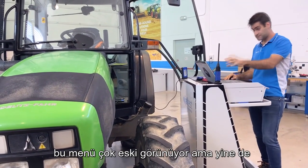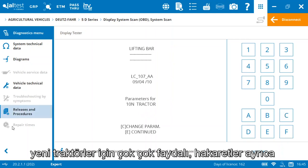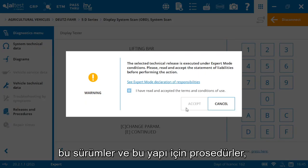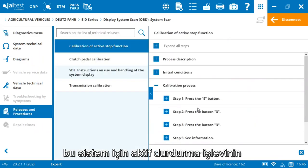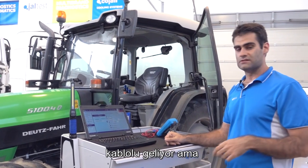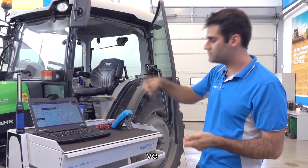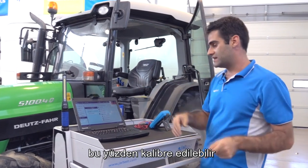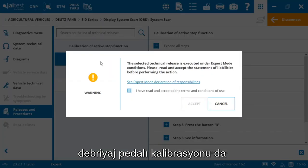Nevertheless, this menu looks very old, but it's still very, very useful for new tractors. Jaltest also includes releases and procedures. These releases and procedures for this tractor, for this system, include how to calibrate many things, like the calibration of the active stop function. Sounds weird, but it has to do with the steering wheel and the amount of movement you need to steer the wheel to the left or to the right. So it also can be calibrated and adjusted. Also, the clutch pedal calibration.